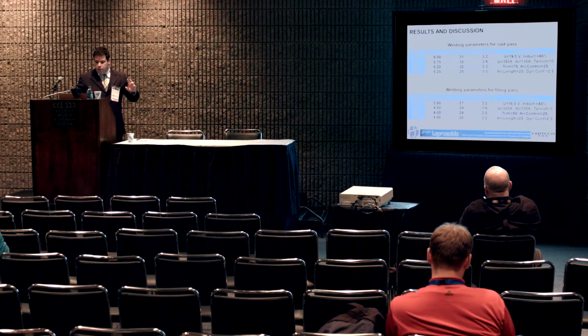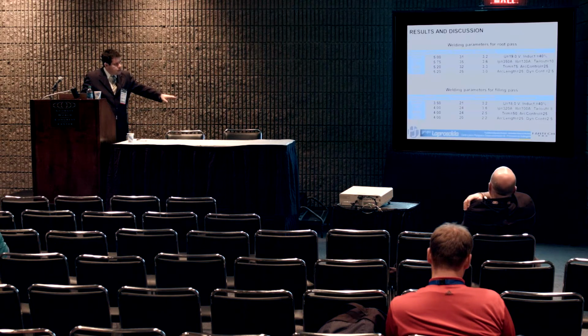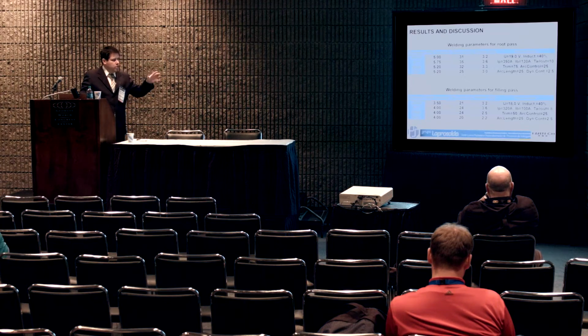So that's the setup we ended with for root pass and for filling pass. All the parameters are there: peak current, base current, trim, arc control, arc length, dynamic control, each one for each manufacturer. That was the best we could achieve, so we left it there on the paper. If you would like to take a look later, you are welcome. That's what we managed to achieve for both root pass and filling pass. If anyone needs to weld, that's it.